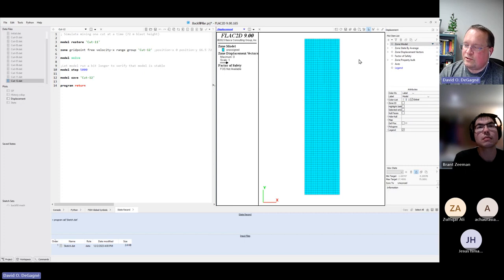It's a good way to make sure everything's behaving correctly by getting some feedback to make sure that you've correctly assigned values. So obviously, if you were to try to run the model at this point, you'd have problems because everything's undefined. This is a way to check that the properties are available, or that the properties that you think are there, like a density of 2,700, are correct and you didn't type in 270.